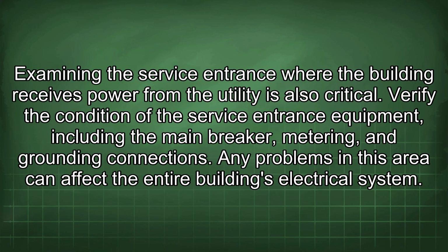Examining the service entrance where the building receives power from the utility is also critical. Verify the condition of the service entrance equipment, including the main breaker, metering, and grounding connections. Any problems in this area can affect the entire building's electrical system.